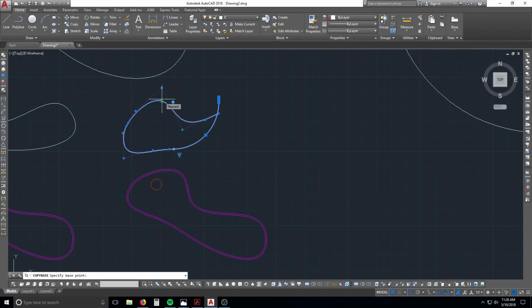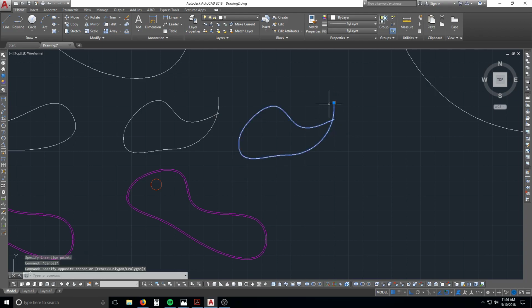That's why I always use that one. So Control Shift C, and then you select your point. Now you've copied it, and you haven't erased it. But now you Control Shift V, and Control Shift V is paste as a block about the insertion point. So see how that little dot, that was our base point, or our insertion point that we identified over here. So you can do a Control X and then paste in as a Control Shift V, or there's a Control Shift C for copy.